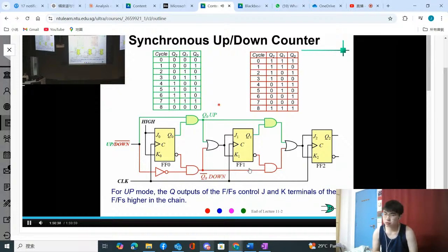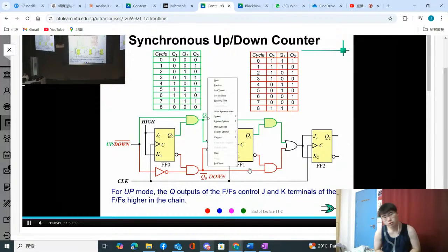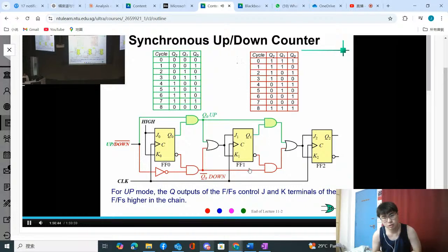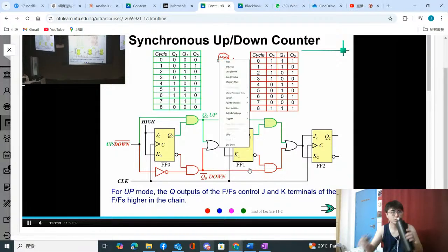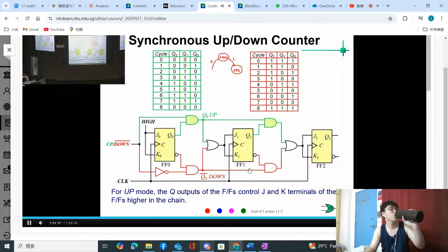You realize that for the finite state machine, you can design using a circle. For example, the first state is called 0, 0, 0. If the input is 1, you will go to where? Go to state 0, 0, 1. If input is 0, you will go to which state? 1, 1, 1. Okay, so you can continue to draw the state diagram.